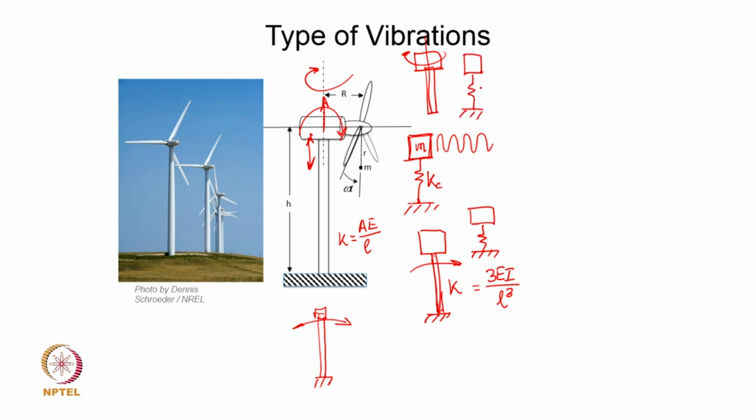That spring will have its own stiffness, the torsional stiffness. I can estimate that torsional stiffness, and we will take an example based on this physical system where T over J is equal to Cθ by L. That is the standard expression we all know from solid mechanics or strength of materials, and so T by θ of course then becomes the torsional stiffness for us. Okay. So, Kt or Kθ is the torsional stiffness, and that becomes then CJ upon L. So, the polar area moment of inertia comes into picture, the length comes into picture, and so based on all the parameters of this physical system you can estimate the torsional stiffness. The mass moment of inertia of this I will be known from the geometry of the nacelle, the mass distribution in the nacelle. So, all of that will give you torsional mode of vibration being investigated.